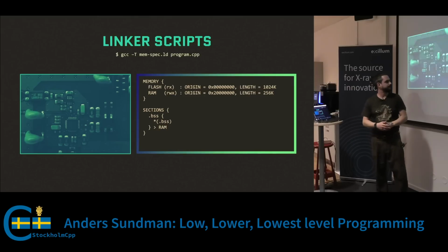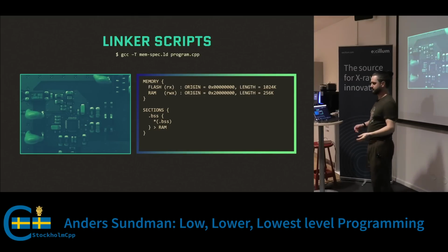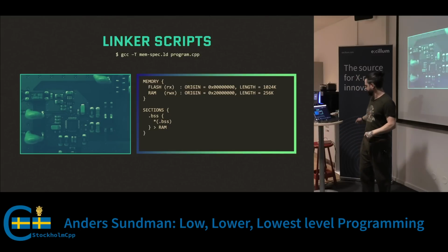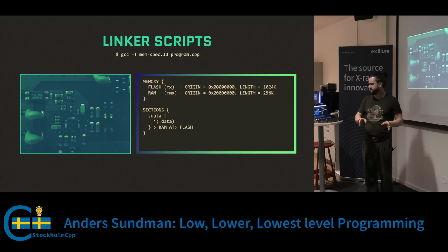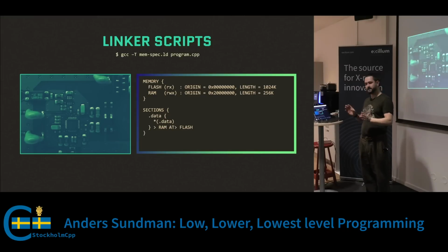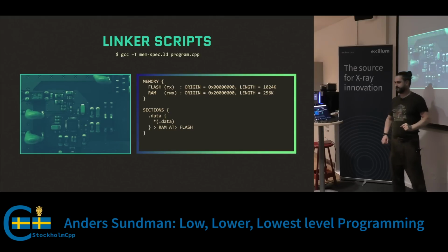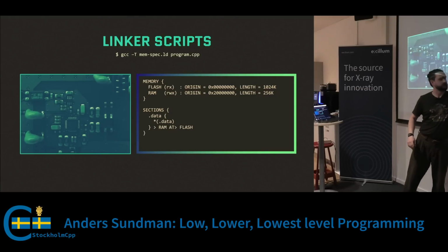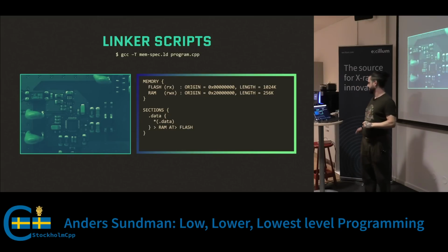Then BSS. It's almost the same thing, but now we put it into RAM, because it's nice and fast, and we don't really have any values that need to persist. Data, well, data is a little bit special, because it has values that we need to persist, so something needs to be in flash. But we want the variables to live in RAM, because that's where we want to edit them. So what you do is you say that the symbols should go into RAM, but actually the values should go into flash. And we will come back to this, because it requires a little bit of finicking later.